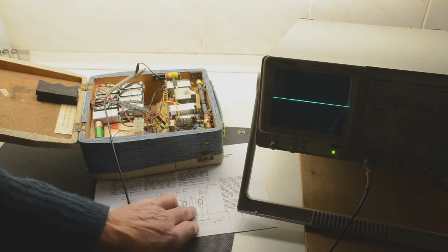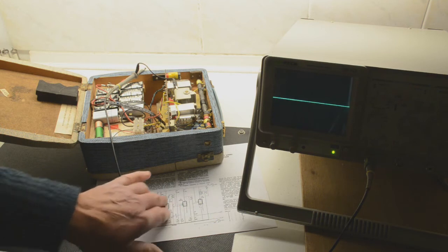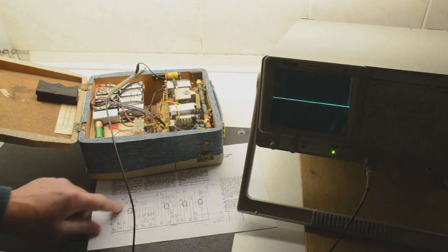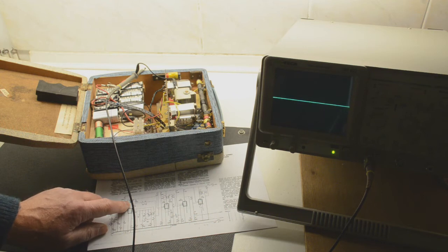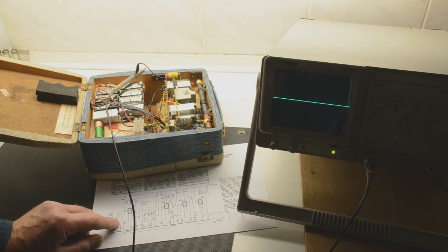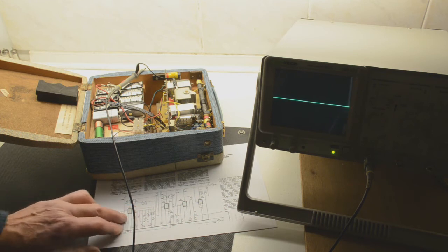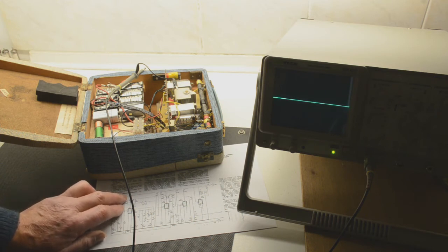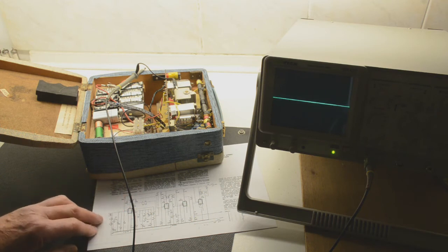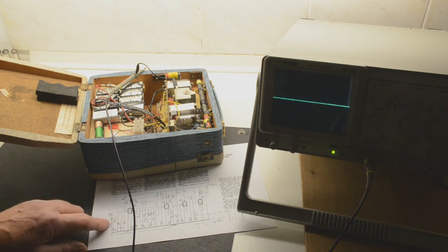That's all we do on this circuit here, but those are the bits, remember. So we've seen the audio, we've seen it's detected, you lose the 465 kilohertz. There's the IF amplifier. So what we're going to do now is move the whole setup around. We've built this on our chassis, so we'll be able to show the oscillator working, and then eventually it mixing it. And our final thing, which we hope will work, is we'll produce an audio signal of a radio wave going straight through the entire system, including our newly built set.